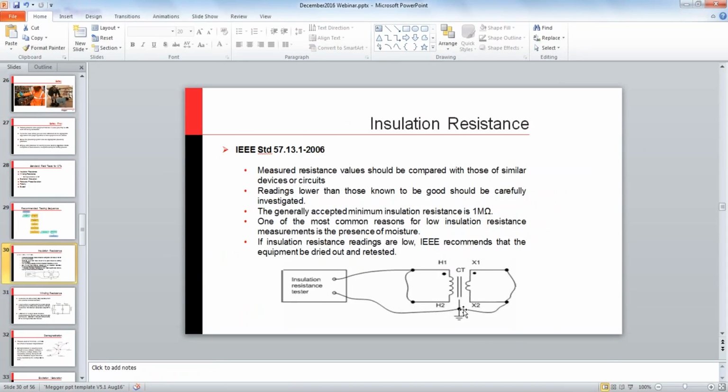You don't have to do any connection changes, none at all. So pretty much you will connect your high side to the high side, your secondary side to the secondary side, and then the switching or the shorting is happening internally. And this ground is the third leg of your input connection, or the ground of the CT tester itself. So that is also taken care of internally.